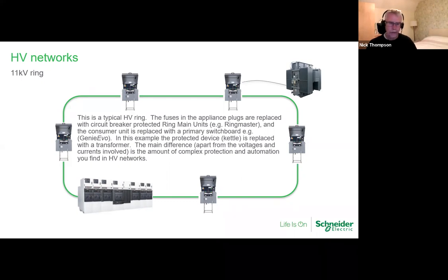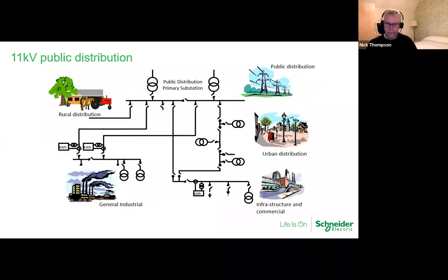And that's typically why we need to look at the different types of networks, which are principally going to be used in distributing HV in private applications. The DNOs have got their own strategies for distributing power around their network. And remember, the DNOs are licensed for managing. They're not licensed to sell. This is distribution network operators in the UK.